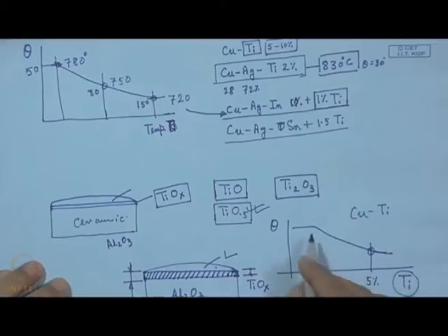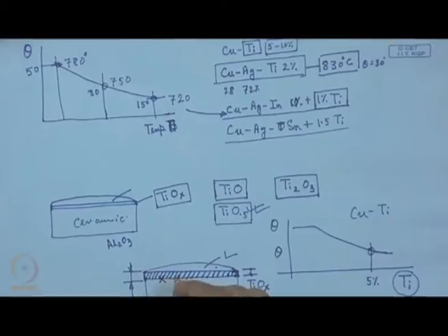So, the main objective in wetting, in deposition of a coating by spontaneous spreading or wetting, is not just getting a good value of theta, but also having good adhesion at this point, and this calls for a fine or very thin reaction layer, which will not affect the stress differential or change in volume at the interface because of a large size.